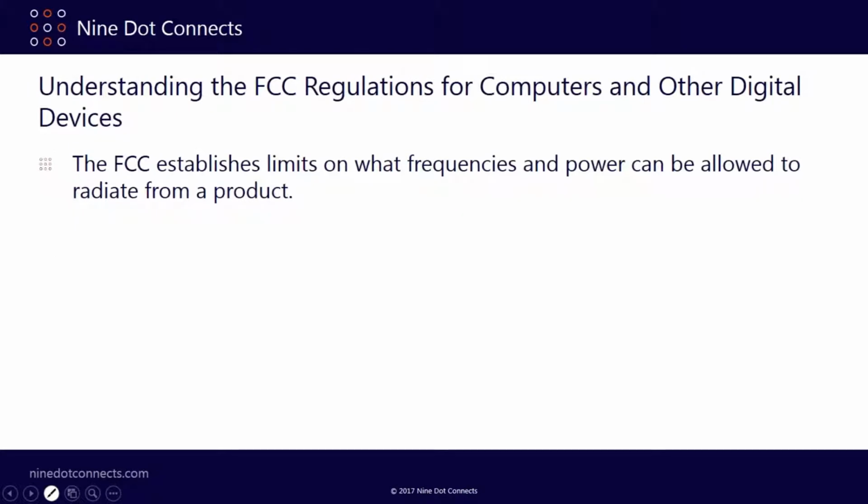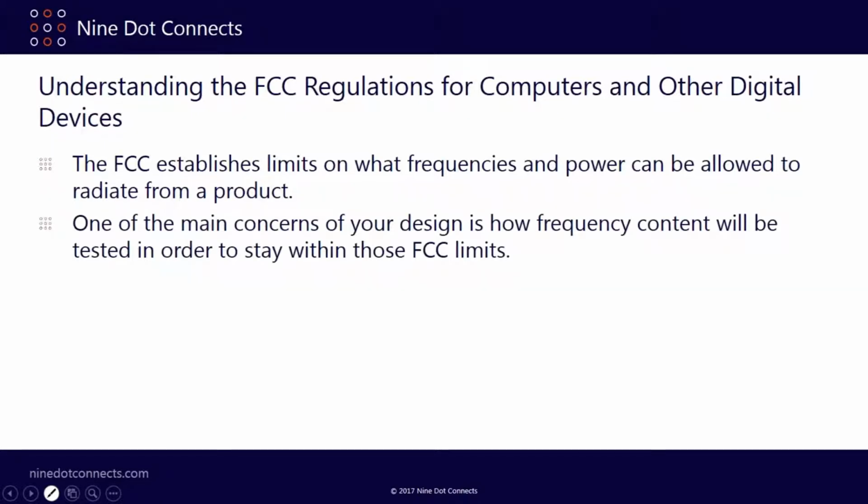I want to identify one thing. We're not here to make you all FCC certification experts, but it is important for you to understand where we're going and why we're going that way. One of the things I want to talk about is the FCC certification for a product, to make sure that it is compatible in today's life, no matter what the situation is. The FCC will establish limits on what frequencies and power can be allowed to radiate from a product. One of the main concerns of your design is how frequency content will be tested in order to stay within those FCC limits.